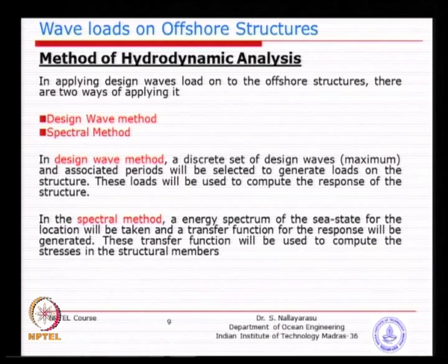The other method of design is basically using the spectral method. That means you observe the waves at the site, collect as much information as possible, and then describe the wave scenario at the site by a frequency versus energy function. Basically, you can plot that this particular wave period has this much wave height and that much probability. So, A, B, C, 3 functions you need to generate.